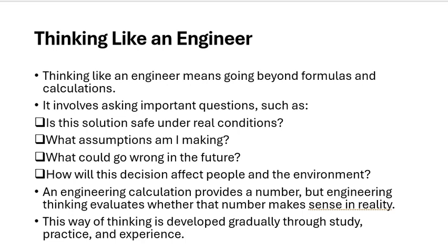It can happen. I don't know. It may not have happened for the last 10 years, but still, it can happen now. So when it does happen, and it will affect my project, what should I do? For example, you are doing concreting, let's say. If there is very heavy rain and you are doing concreting in open, they don't usually do it, because you will have water coming from the top and you cannot stop it. So it will affect your mix.